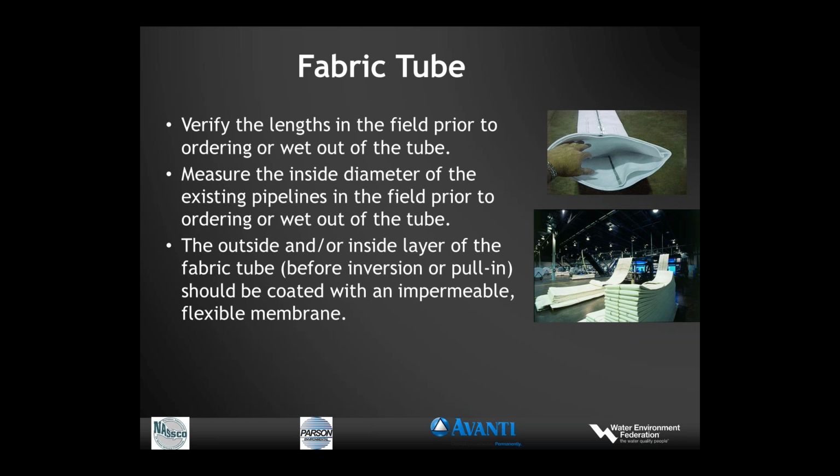And the contractor should verify in the field the length from manhole to manhole prior to ordering or prior to the wet out of the tube. Very important, this is a quality issue because it happens periodically where the shot comes up short, and that can ruin your entire day. In addition, the contractor should measure the inside diameter of the existing pipelines prior to ordering the tube or wet out of the tube.